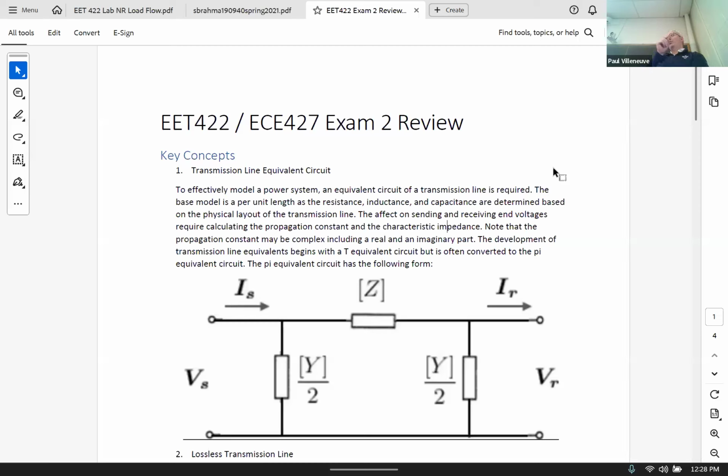At the beginning, when you're writing delta P2, you always let i equal 2, to give you that memory that i is going to be equal to 2. So anytime I see i, I'm substituting there. It's easy to mix up the i and the k because they are so close. Putting in the k is not so bad as long as I have the i specified well. So usually what helps me with the power balance equations is to identify what the i variable is and then just walk through the ks.